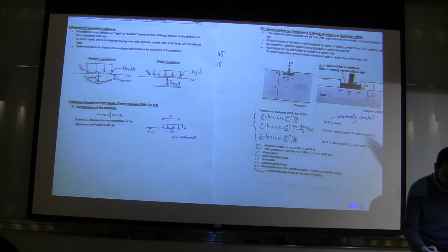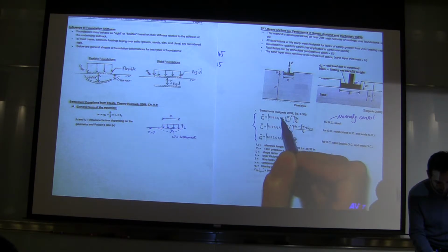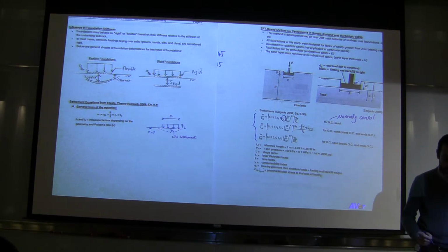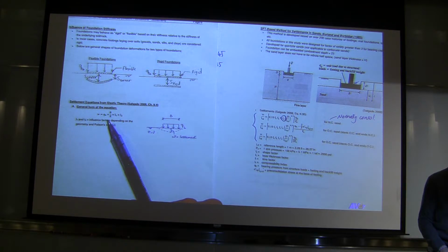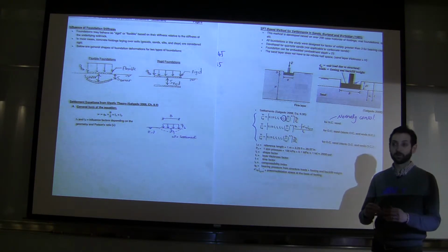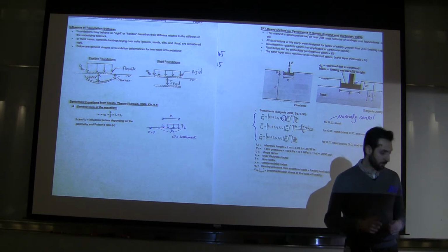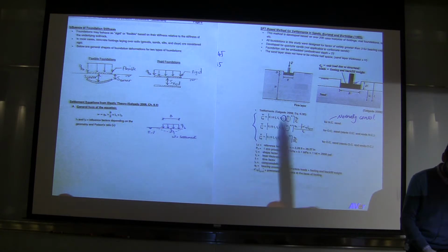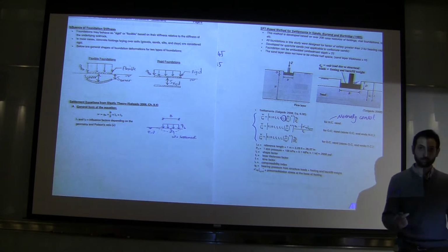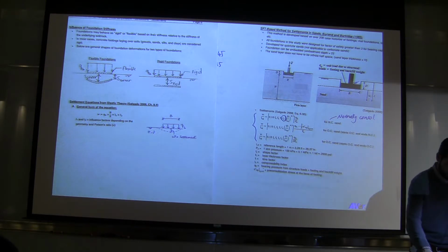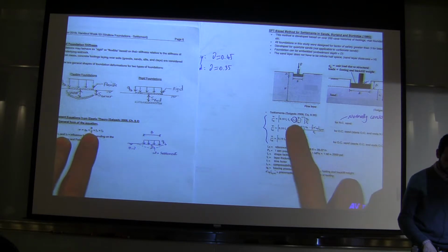And that is done by these guys who developed this equation. They added this I sub c here to represent the elastic modulus in this equation. So technically, if your sand gets stronger, I sub c should reduce, because I sub c is in the denominator here and E is in the denominator, so if E increases, I sub c should decrease.